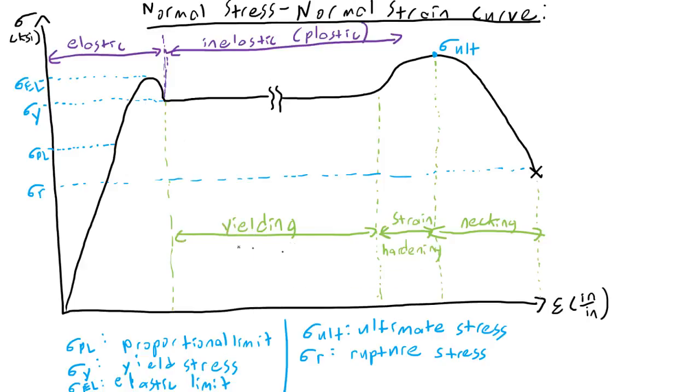As a reminder, the Young's modulus, or the elastic modulus, E, is going to be the slope of the linear portion here. However, we need a way of estimating this. The problem with estimating the Young's modulus from the slope of this line is that it's often vague exactly where this curve stops being linear.